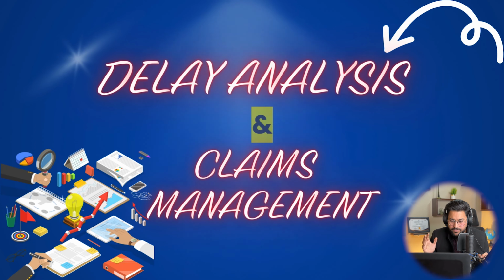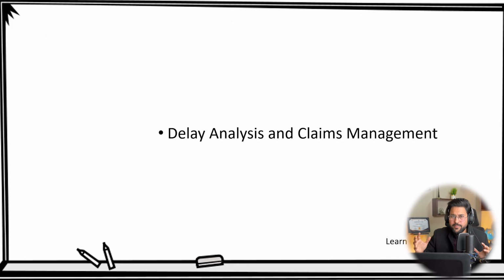Recovery schedule is something for when you are optimistic, like you are positive that you can even make your project completion within 1 year, right? 6 months are gone, but progress is not up to that level. But now in the next 6 months you can achieve 75% by fast tracking, by scheduling. That is called your recovery schedule. In recovery schedule, you are not going to disturb your completion date, but revise the schedule.